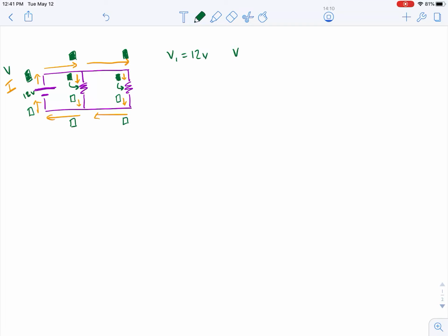What is the voltage across resistor 2? What is the voltage used by resistor 2? What is the voltage drop for resistor 2? These are all ways that you can hear or read that worded. It would be 12 volts. So we say for a parallel circuit, it's the voltage that is the same for all the different parts of our circuit. Because they only experience the one resistor, they give all 12 volts to the device that they encounter.